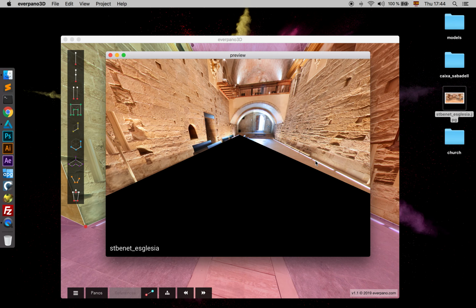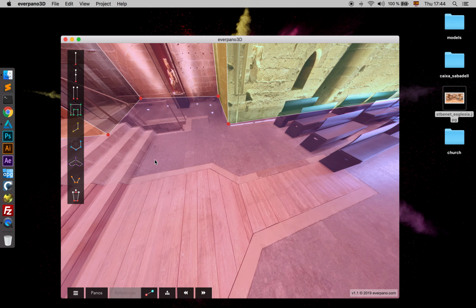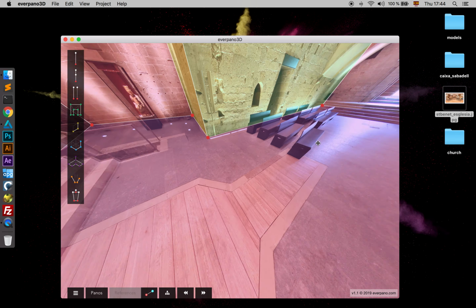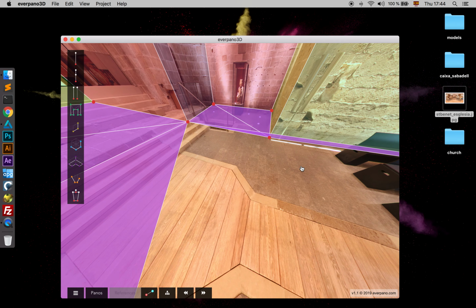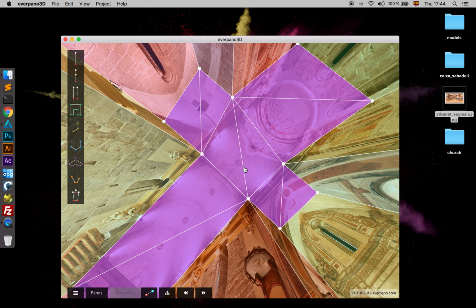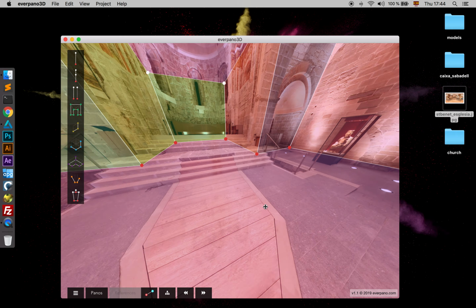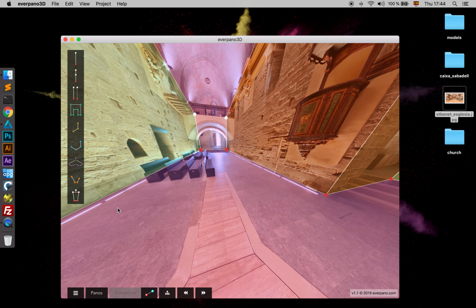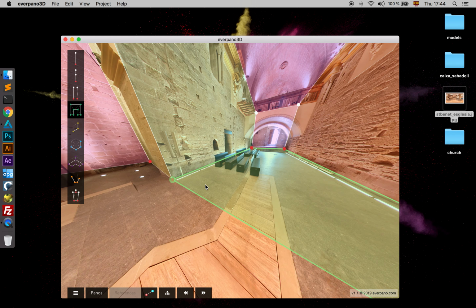Okay, so we have a big hole here, so just check out what happened. I think that now we have a really big polygon on the ground, so we just press Shift A, and yeah, we can see that the triangulation result is very bad. It doesn't happen on the roof, sorry, because we have it farther away, so it's not using all the space. So please just remove it, and as I told you before, when we have this situation, what we have to do is to simplify it in smaller pieces.